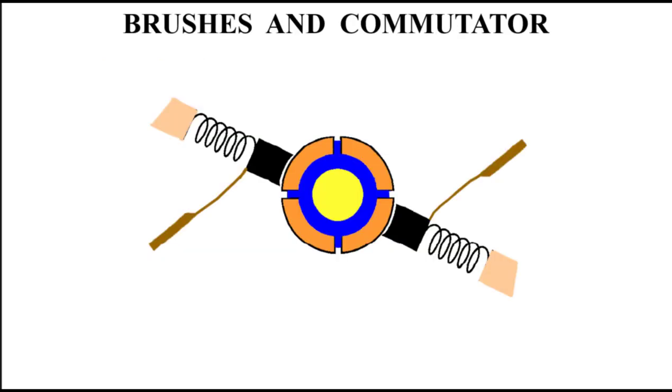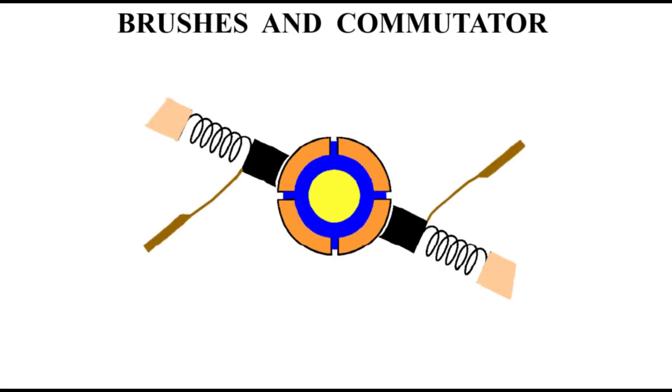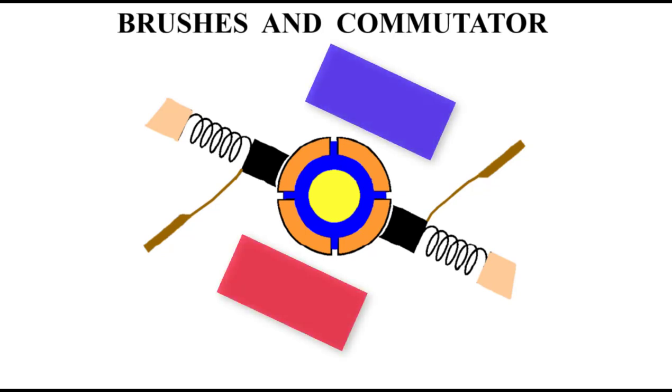So in the armature, the rotating part of the motor, we have that electromagnet. We have coils of wire and we have steel. Typically we have laminated steel in the armature, and we wrap coils of wire around it and run current through it to make an electromagnet. And in doing that, we situate that in the middle of north and south poles that are on the outer side of the motor, and those forces that are in play want to create that movement.